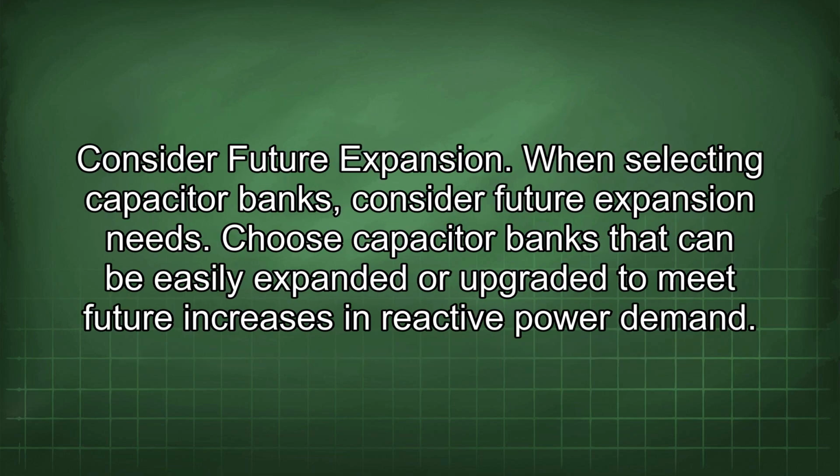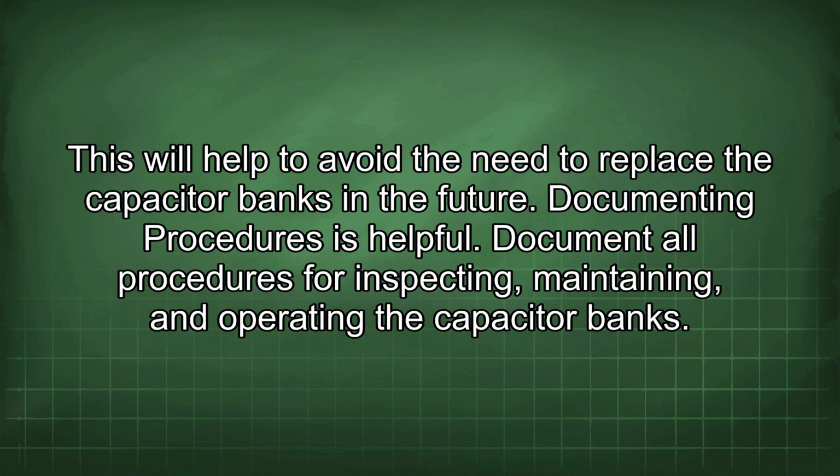Consider future expansion. When selecting capacitor banks, consider future expansion needs. Choose capacitor banks that can be easily expanded or upgraded to meet future increases in reactive power demand. This will help to avoid the need to replace the capacitor banks in the future.